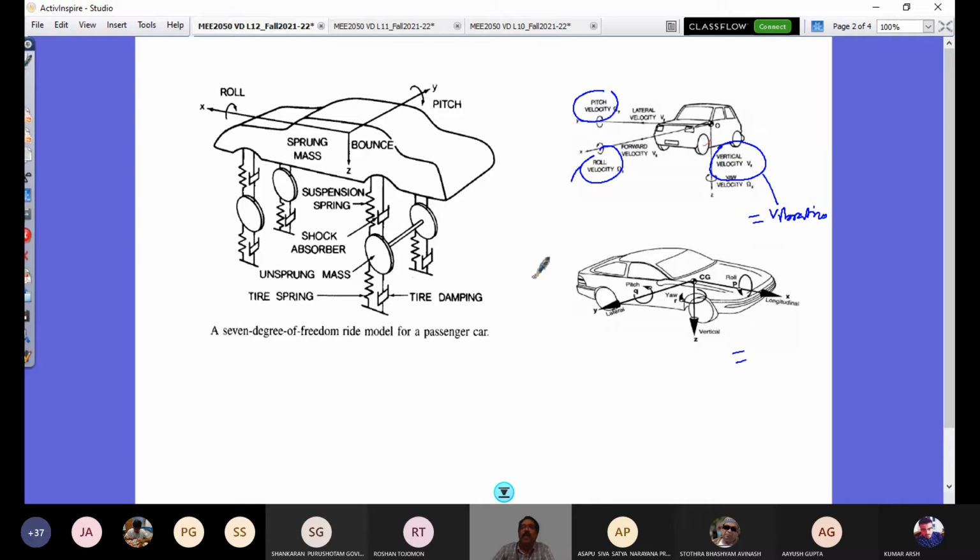If that is so, a full vehicle can be discretized or modeled with many degrees of freedom. In fact, to model a passenger car in finite element analysis, you need an infinite number of degrees of freedom because this structure is a continuum. That is the advantage of the numerical method, finite element analysis. The vehicle would be completely modeled and discretized with lakhs and lakhs of nodes and elements, and then the vehicle would be analyzed. You can see many such applications in the literature.